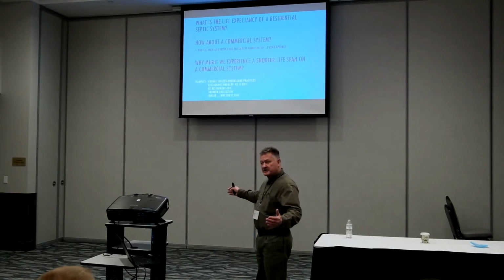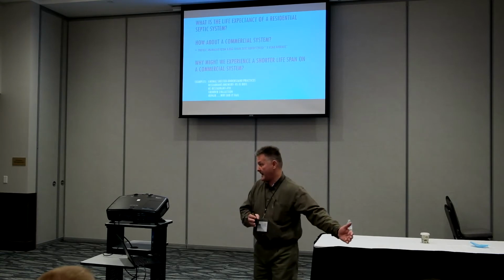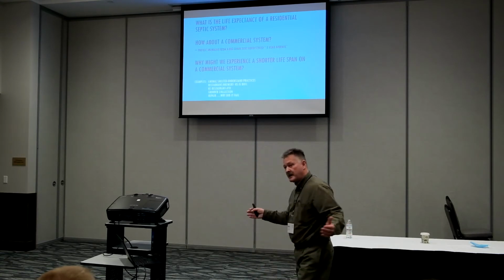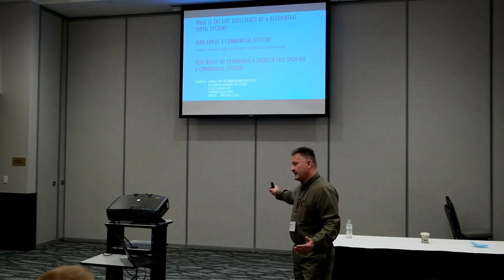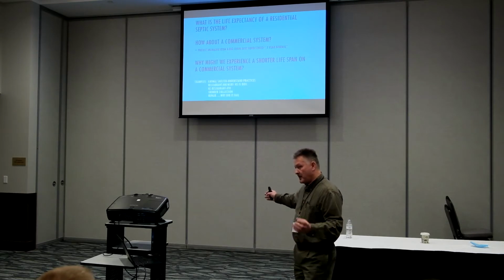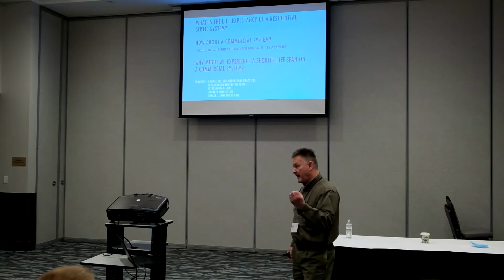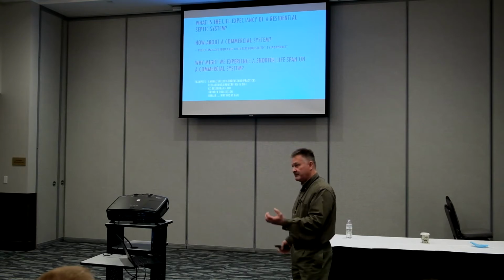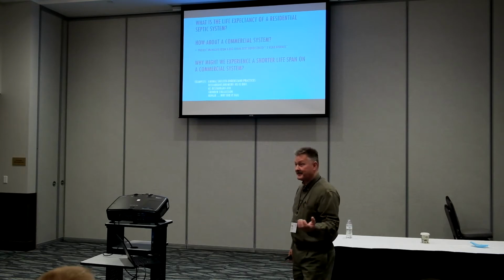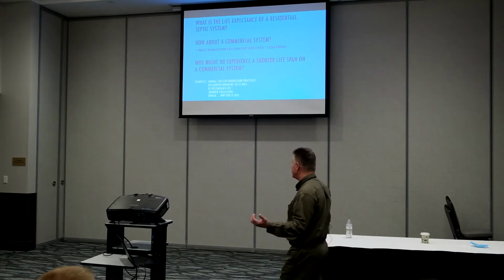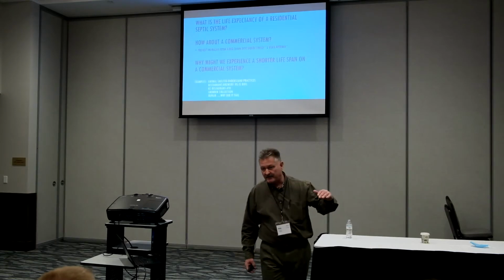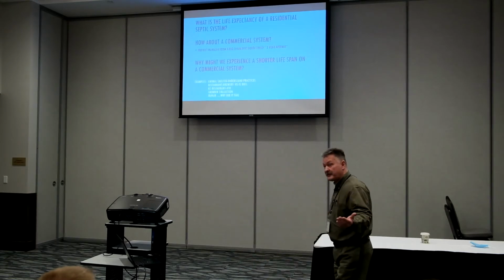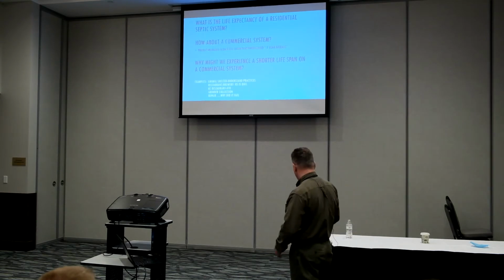Some of our treatment systems that we design can inadvertently create high-strength wastewater. So for instance, we have a community on-site treatment system, and say we have grinder collection. Well, if we don't understand what happens with a grinder pump, it grinds everything into a slurry, puts a lot of those organics into solution, and it's very tough to get out. It's kind of like orange juice. You can screen out the pulp, but you still have the orange. And so you've got to rely on the bacteria to degrade that. So for instance, with a grinder collection, if we design a system based on a BOD of 150, we're realistically probably going to have 300 going into that system, so it can create a problem.